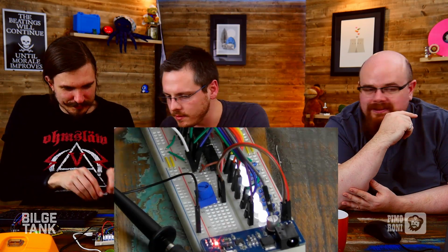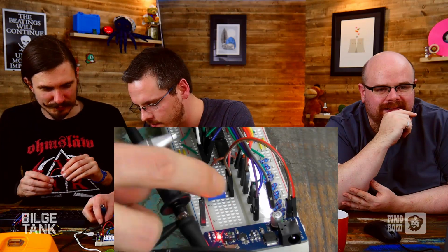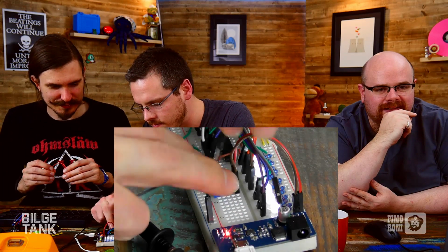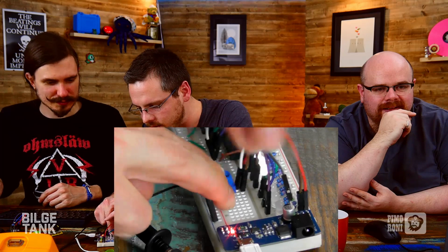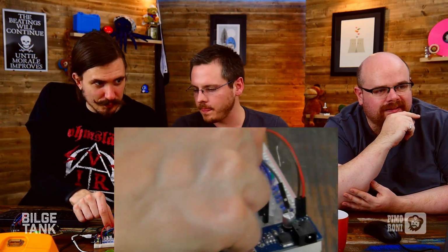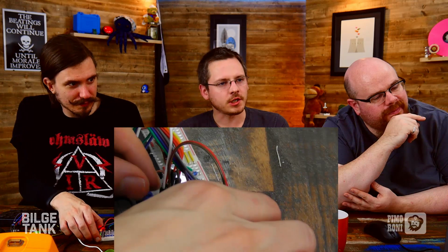Yeah. So I want to use your ADC to measure the value of my little potentiometer. Oh, you can go straight in. Tap it in there. Oh, there we go. There you go. So now, Phil's just hooked up a potentiometer between the 3v3 rail and ground, and we've connected the wiper directly to the input of the ADC.